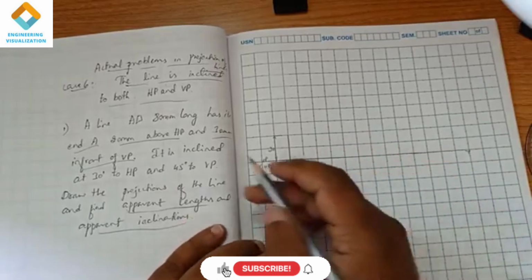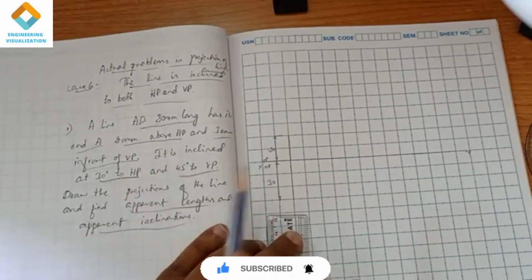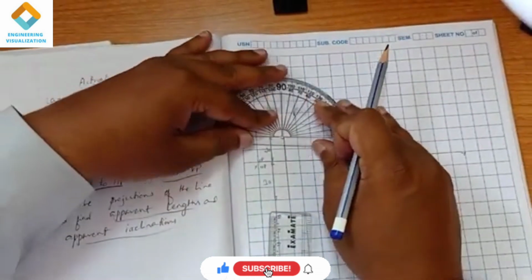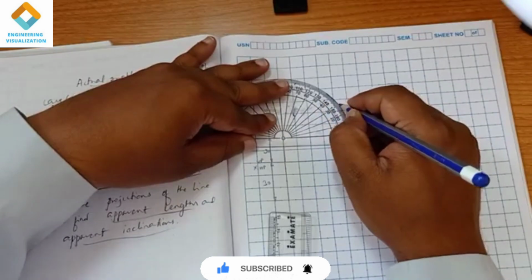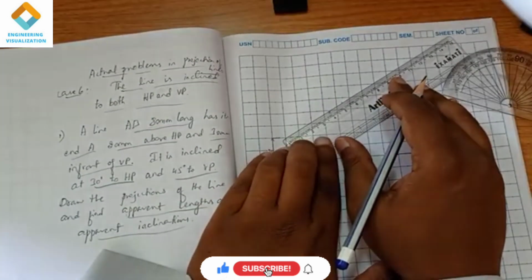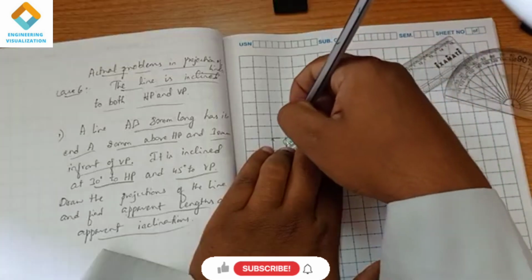Here the length of the line is 80 mm, so AB is the true length. You have to find the apparent lengths. The angles of inclination given are 30 degrees to HP and 45 degrees to VP. First we take the 30 degree inclination: mark 30 degrees and draw a line of length 80. From this point you have to mark till 80, and 80 means 8 centimeters.